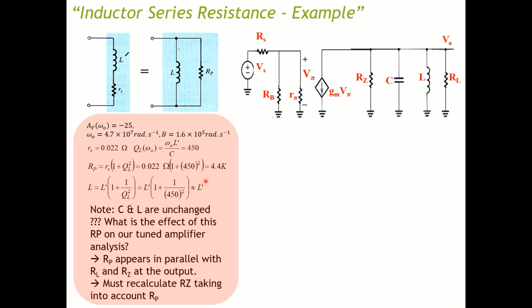So here we calculate RP. When you couple RP into this model, effectively you have changed your load resistance into RL in parallel with RP.